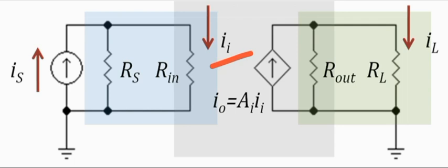Now once II enters the current amplifier, II, remember, is approximately equal to Is, what is being sourced. So when this current II enters the current amplifier, it gets amplified with the current gain indicated by AI, and the output current, or amplified current, I naught will be equal to gain times the input current II.